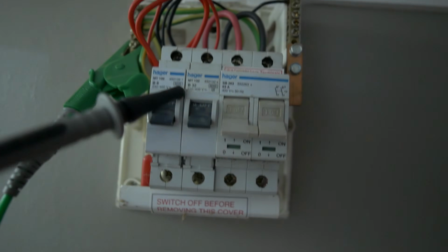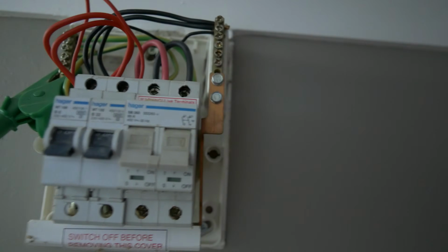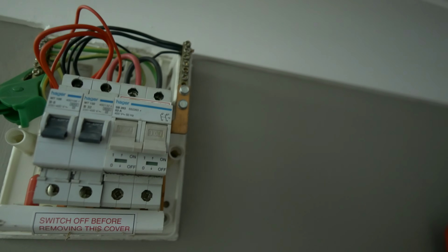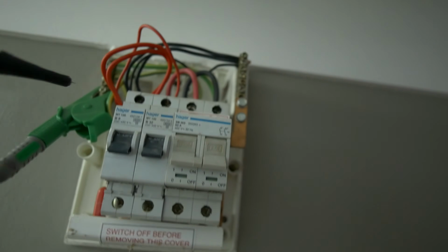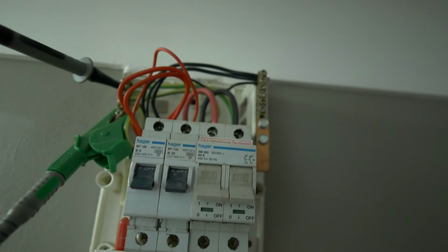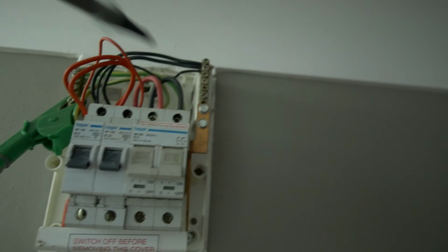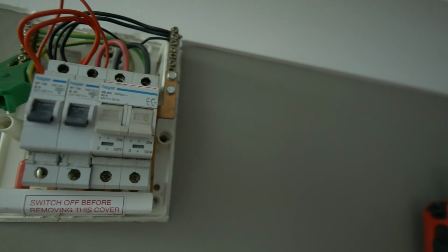So you can see that's dropped the socket circuit off, if it will focus, to 23 megaohm as we got on the lighting circuit, and that's finding the same path through that neutral connection in the neutral bar. So although we've got the lines isolated, we have still essentially got those neutrals tied together. So there's a path there. When you're doing your insulation resistance testing on a circuit by circuit basis, it's important that you understand where those parallel connections can be. Obviously with the CPCs and your parallel paths on the earthing, they kind of have to remain, but you need to remember to separate apart your line and neutrals if you want to get a true value of insulation resistance on those circuits.